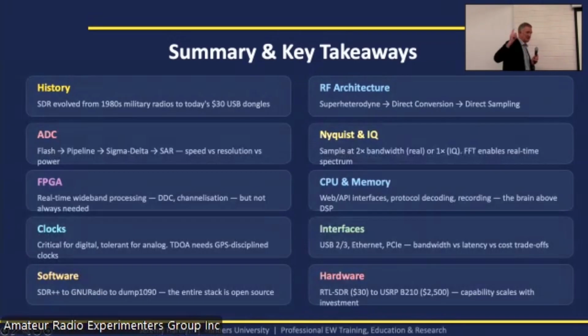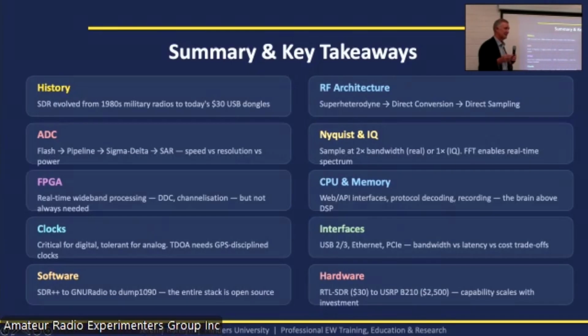In the analog sense, there are 2 versions here, and I'll just touch on them. There's an analog conversion that happens inside the A to D converter, which means that it has a signal passed through to it at 90 degrees, which allows it to calculate the Q component. When it's done in the digital, it actually comes out real, and it's then mathematically converted. So it becomes an interesting issue associated with how they apply the conversions.